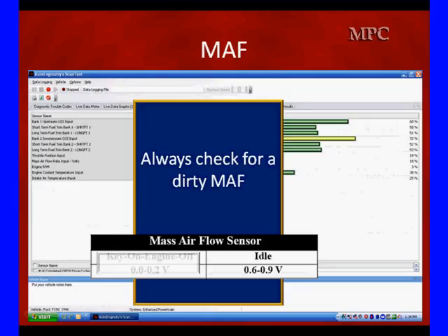Use nothing that leaves an oily deposit to attract more dirt. But it can be true of any manufacturer. They all get dirty airflows at some time or other. Know what's normal and make sure you verify that. They're a frequent source of off-idle, light-load, lean air codes.